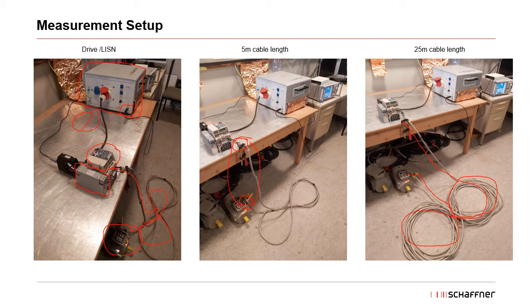One additional test is with different switching frequencies in the drive. So we are going to change from 2 kilohertz to 5 kilohertz and to 8 kilohertz and show you different kinds of measurements for this type of motor switching frequency changes.